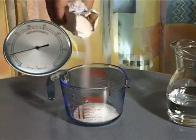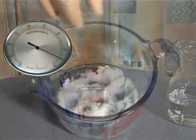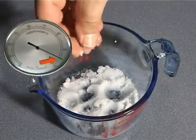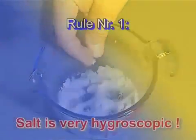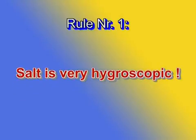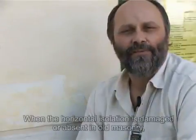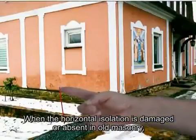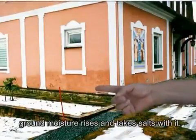In a very dry indoor climate, salt trickles like fine sand. When the air becomes moister, salt turns stickier. Rule number 1, salt is very hygroscopic. When the horizontal isolation is damaged or absent in old masonry, ground moisture rises and takes salts with it.